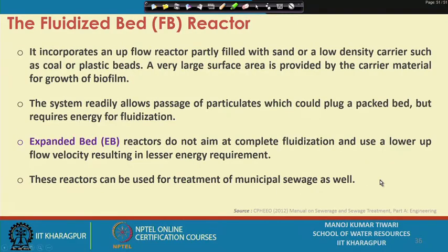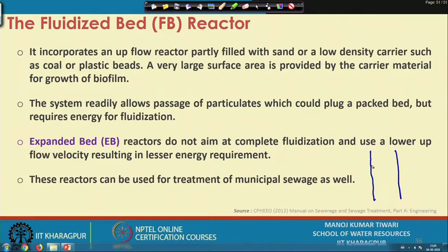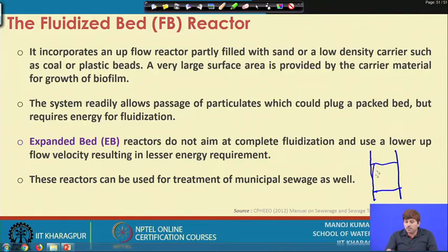Then we have the fluidized bed reactor. This fluidized bed reactor essentially incorporates an upflow reactor partly filled with sand or a very low density carrier. The basic difference between a packed bed and a fluidized bed reactor is that in a packed bed, or whenever we have packed media, we pack the media inside the reactor and then allow the flow either from the top or from the bottom, depending on the characteristics, and the flow passes through while the biomass and media remain in place.